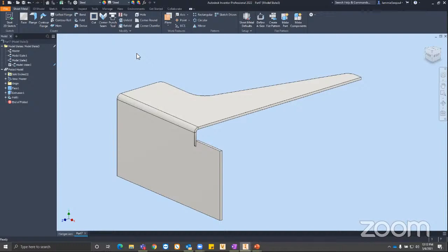But right now, this is just a generic cut, so I'm just going to use a 3D cut. Okay, yeah. Because I know that in the cut tool, there's a special option for cutting around bends, so I can see that being useful. But if it's just a generic cut on a flat profile, extrude or cut is pretty much the same thing. Exactly. Thank you for that question.